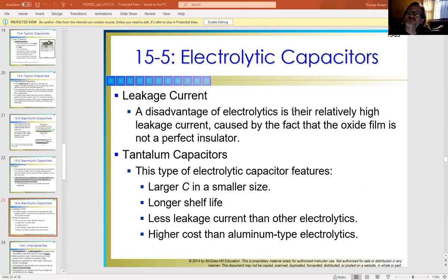You've got this mass storage potential, but because of that, at the same time, it's also not the best insulator in the world, so it doesn't work ideally. If we were using one of the mica ones or something like that, we wouldn't have to worry so much about that. But at the same time, we're not going to get a mica capacitor in a size like this.